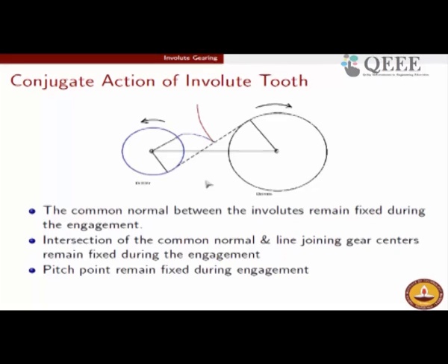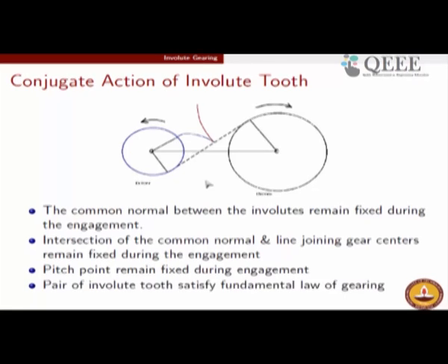And since this tooth profile is now proven to satisfy the fundamental law of gearing, without further ado we can say that this tooth profile will maintain a constant velocity ratio during the entire process of engagement. So that is the proof that I wanted to go through.